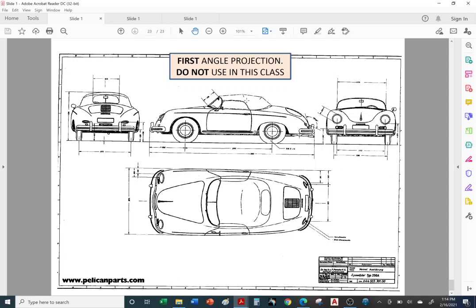So in order to be able to handle all the weight of the cargo, you have to remove the floor beams, similar to what you see in a house, the floor beams or joists, and replace them with something stiffer and stronger so they can handle the weight. So we're looking at this drawing of a beam for this cargo aircraft, and it didn't make sense to us.